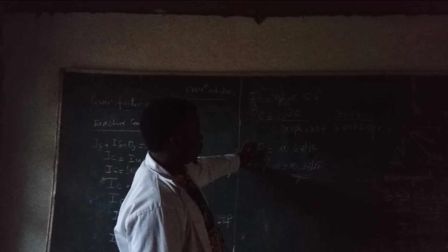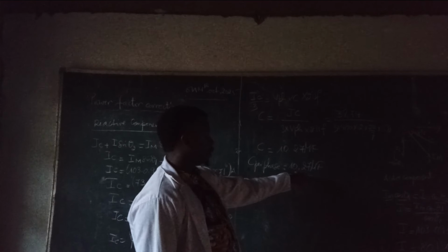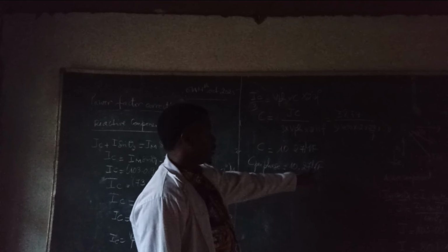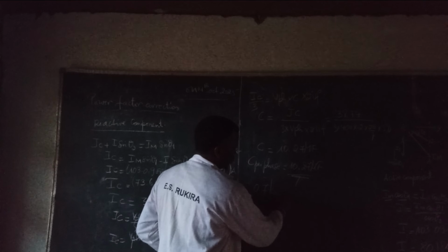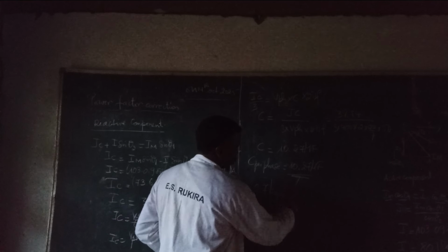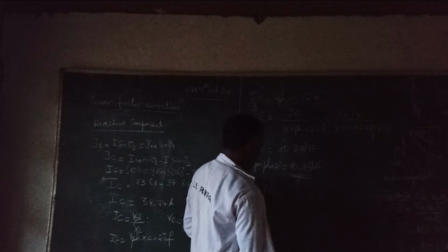Every phase must be fitted with a 10.27 microfarad capacitor, for our power factor to rise from 0.7 lagging to 0.9 lagging.